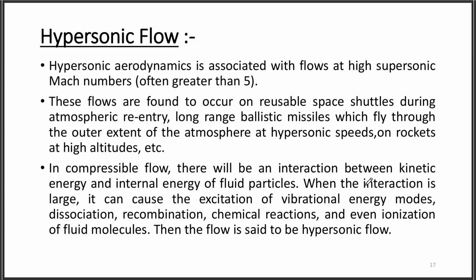Now we have to see what hypersonic flow is. Generally flow greater than Mach number 1 is called supersonic flow. But hypersonic flow is generally associated with Mach number greater than 5. It is not like that when Mach number suddenly becomes greater than 5, the flow becomes hypersonic. It is not defined like that. There are some important characteristics corresponding to hypersonic flow.